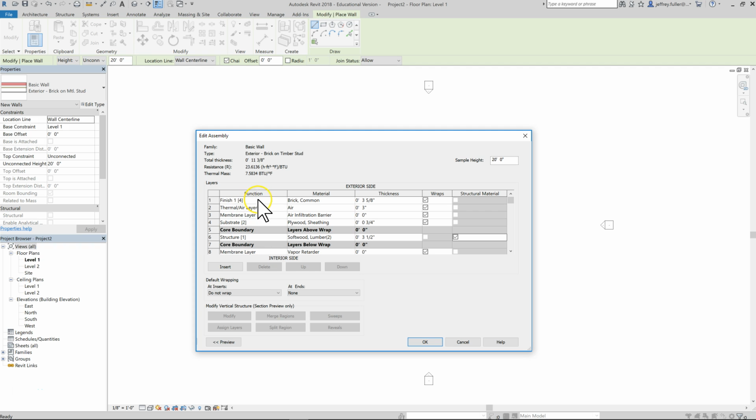Now, let's see, the selection for the exterior finish, we selected finish 1, which is a priority level number 4. It gets a higher priority than the interior finish, which is finish number 2, and priority level of number 5. So it would override any priorities regarding the interior dimension or interior material. So our finish, of course, is a brick common.